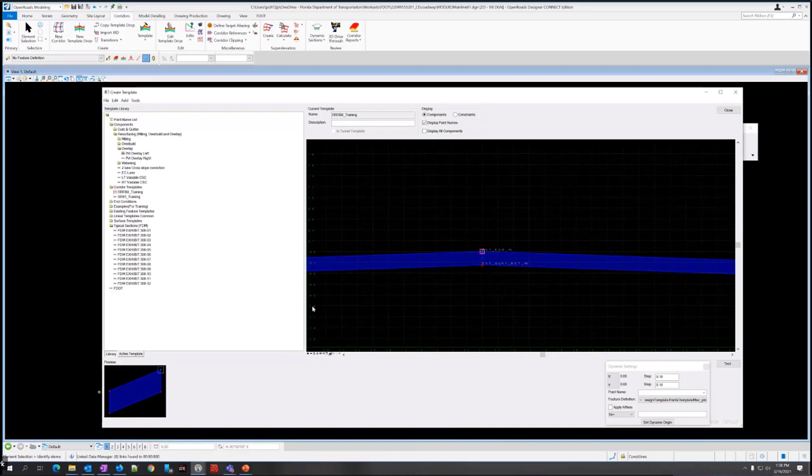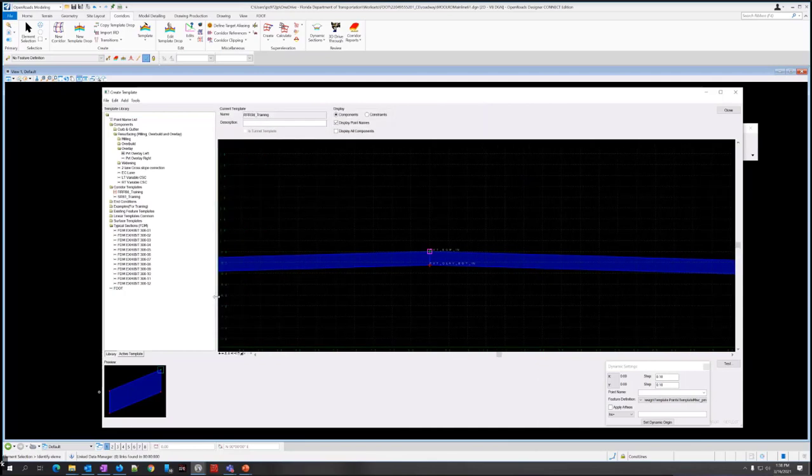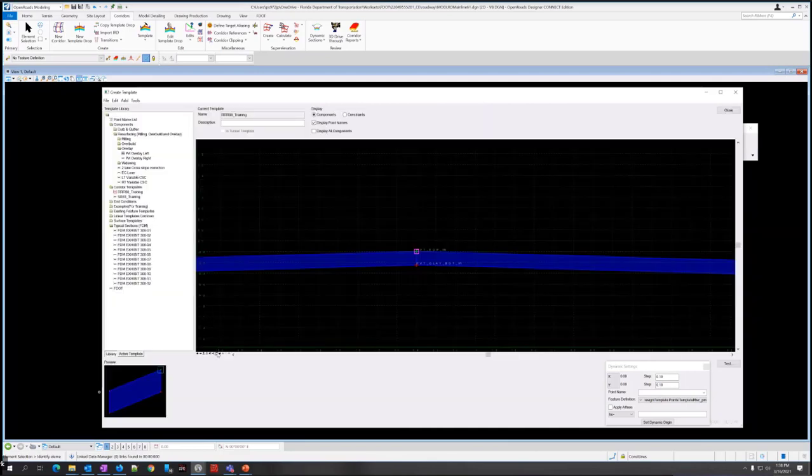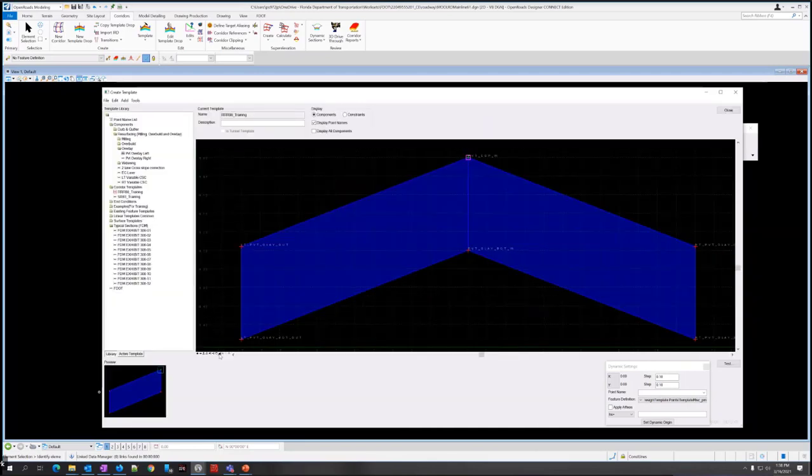And you can fit view. This is similar to the way ORD works, and you have some of the view controls down here. So a little mountain looking icon will fit view. Some of your view controls are down here on the left, so it's kind of its own thing. All right, so we fit that view. There's our pavement. That brings us to the end of step 4.